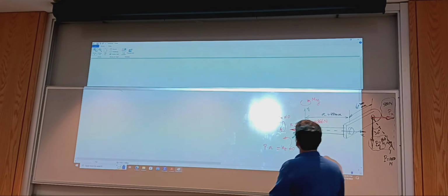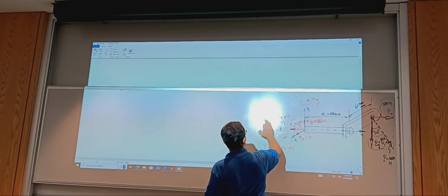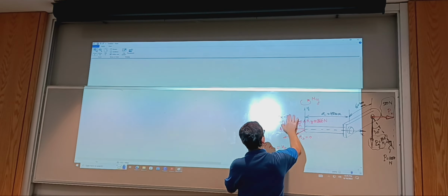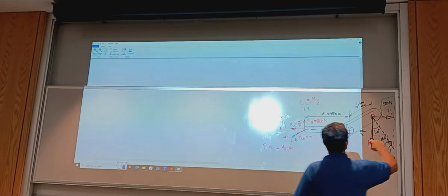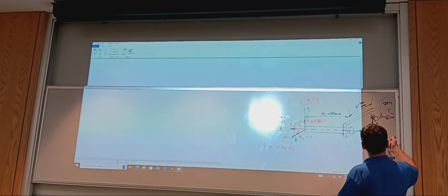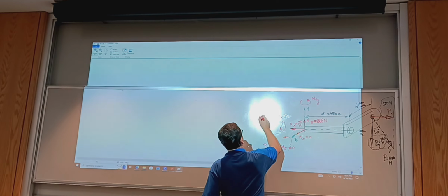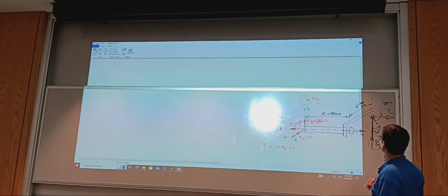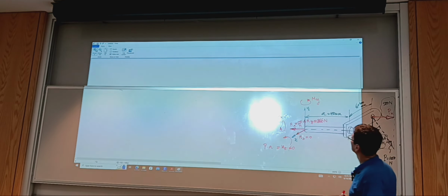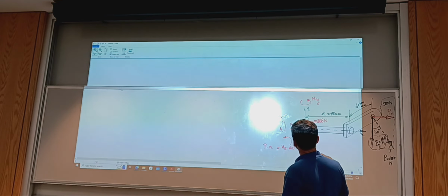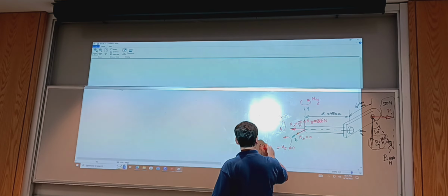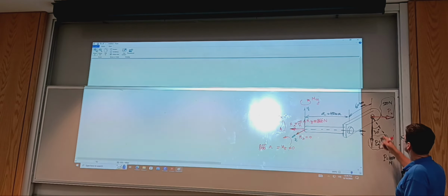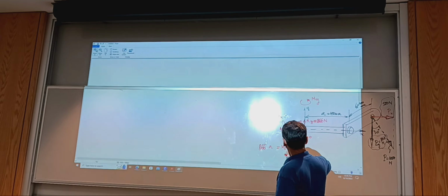So the torque or the twist of the bar is going to be by this torque that was P before, now 1,000, now it's 866 times B. And then I said we have a moment that is no longer 0. Here too, instead of P times A, I'm saying 866. Could have said P times cosine of 30 degrees. Okay, and it's not 0.